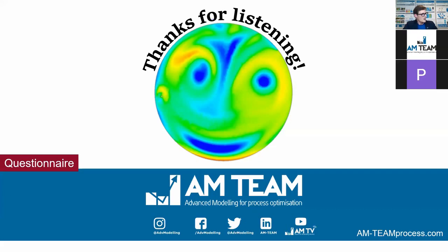That's a good answer, Wim. We can even go to a level where we can model capillary motion, so not really convective, but capillary. That is the level of resolution you can go into. The good thing about CFD is that scale is not really a limit to your CFD models, and there's a variety of CFD models available for every kind of scale. Of course, for capillary you will not use turbulence models, but different ones. But it can handle it. It's all Navier-Stokes equations.